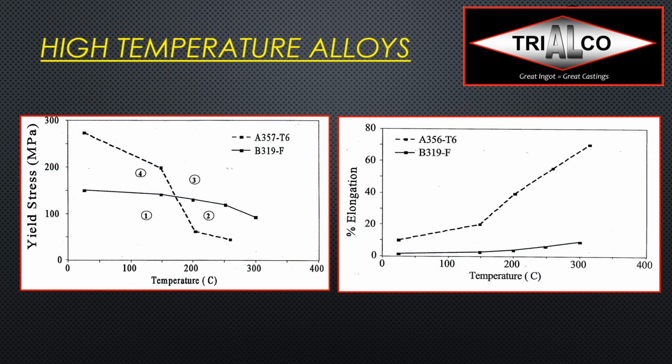So what does the copper really do in high temperature alloys? As I mentioned before, the typical aluminum silicon magnesium alloy, with its Mg2Si hardening, loses its strength very quickly, and especially after about 150 degrees Celsius, we can see a pretty dramatic drop. That's what we see in the red arrow here. Very quickly, I'm going from 200 megapascal strength at 150 degrees, and at 200 degrees Celsius, I'm down to just about 50. So I have lost 75% of my strength in just 50 degrees Celsius.